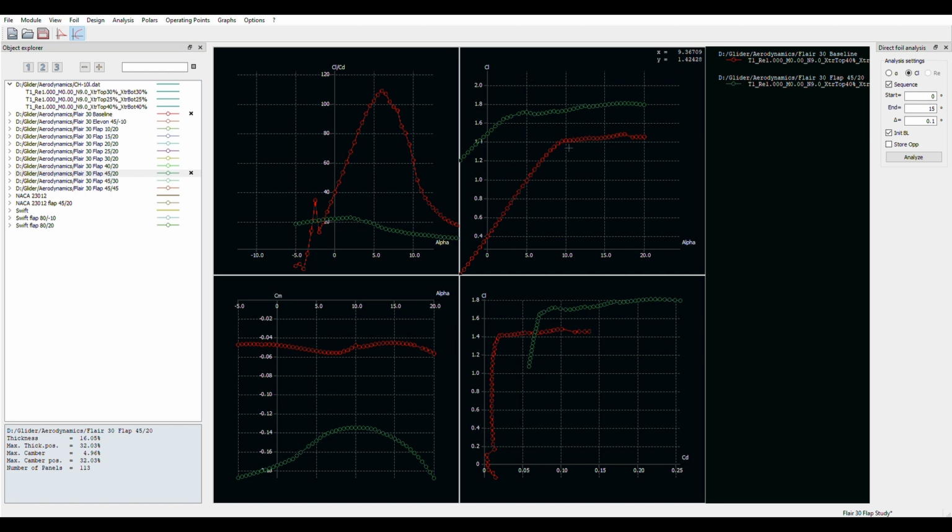And I looked at this and I went, holy cow, what's going on? Look at this. They had a stall angle of attack about 10 degrees. Now the stall angle of attack is 5 degrees or less. The stall looks like it actually starts around 2.5 or 3 degrees, and a modest increase in lift. It went from 1.4 to 1. I'll give them benefit of the doubt that they make it all the way over to here, maybe 1.7. So 3/10 on the CL, and the lift curve slope is flatter.